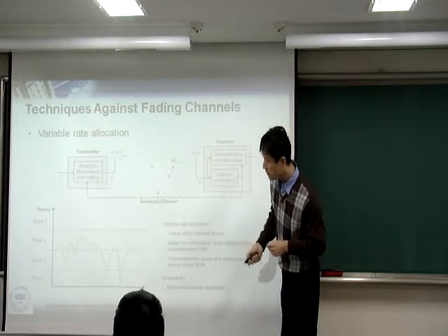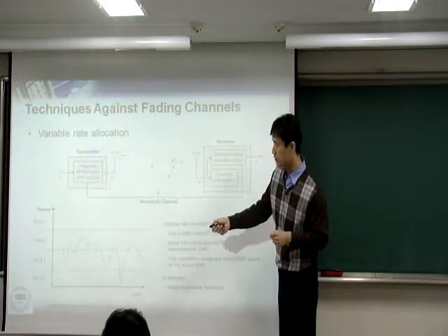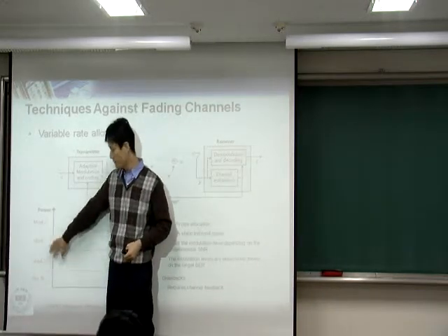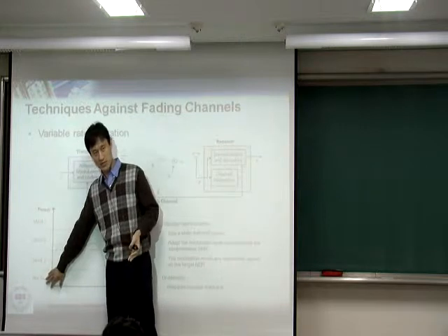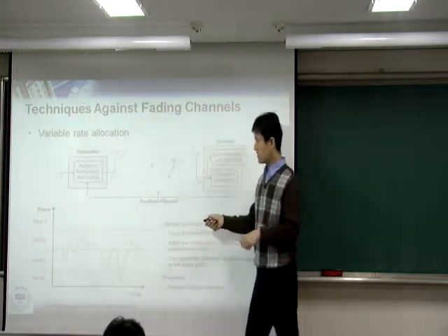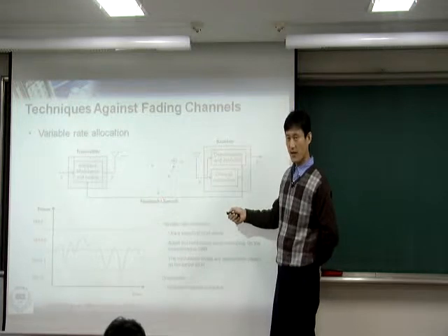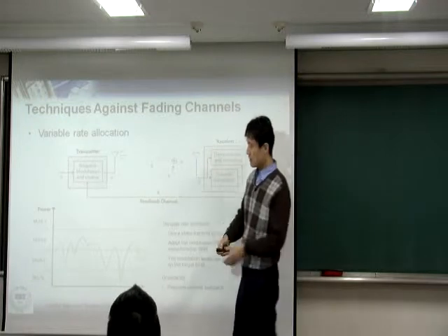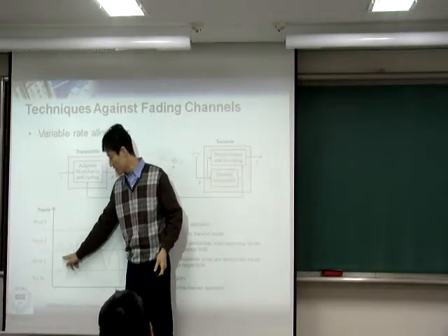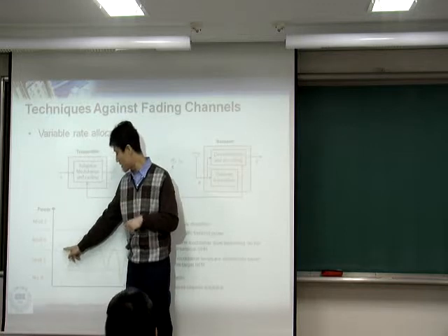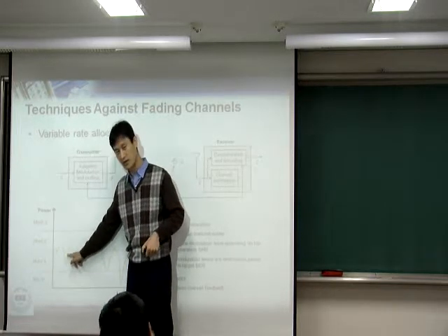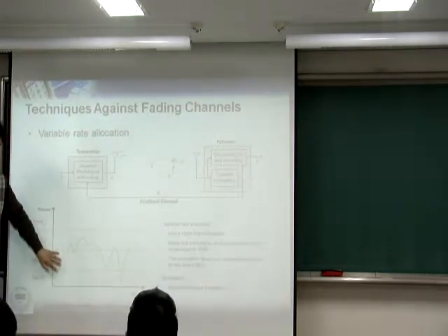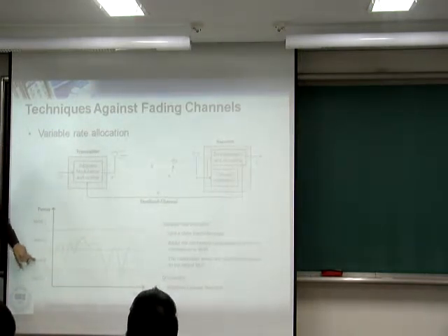Here is the mode TX, mode 1, 2, 3. So that means it's modulation 1, modulation 2, modulation 3. This is no transmission. What that means is, based on this fading, the instantaneous H, if you think that my current status of H is here somewhere, then my channel is a little bit bad in a certain region, so I'm going to use this modulation.